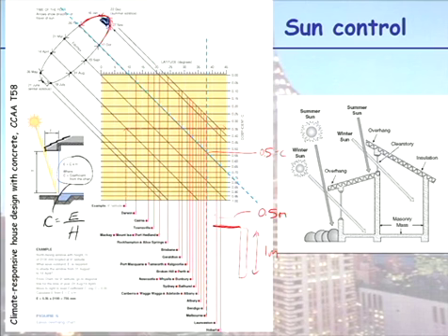You would then come down this line here, and you can see your C coefficient here is of the order of 0.3. So you would only need an awning of 0.3 metres in order to block out all your summer sun but allow your winter sun into the building. So very simple. There'll probably be lots of computer packages you can use to tell you.